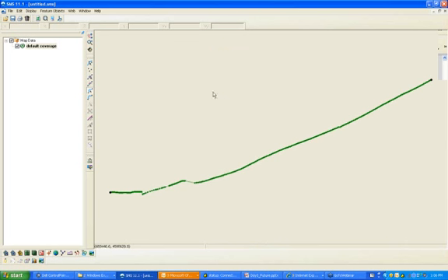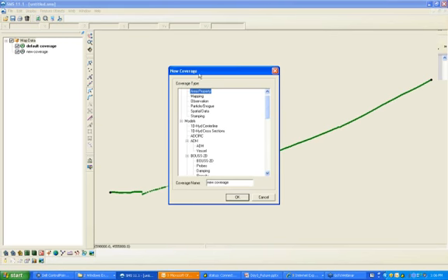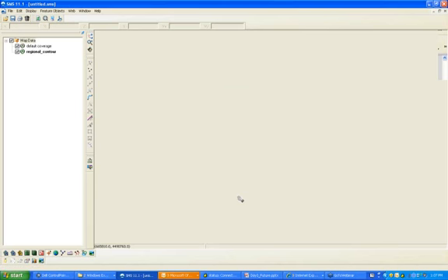Remember, next, if we have a regional contour, we have to open up a new coverage. So to do that, we need to go to Map Data. We're going to go to New Coverage. And we're going to scroll all the way down to Gencade, which is here. And we're just going to rename the coverage name. I like to just name it Regional Contour since it's easy to remember what it is. And we'll click OK. And now we have that new coverage created.